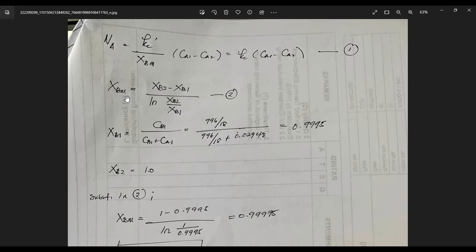So you have the mole fraction of your water, B, in your solution of water and naphthalene once your water has diffused to naphthalene already. So this is your X sub B1, your 0.995. Your X sub B2, the portion in which you have the full diffusion already, you have already at 1.0.